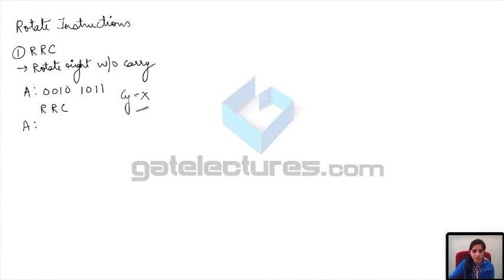The status of the carry flag is don't care for us. When we rotate the contents of the accumulator towards the right, the LSB is going to become the MSB, and every other bit is going to shift right by one place. So what is going to be the new contents of the accumulator? Fine. So this is how RRC is going to work. This is a 1 byte instruction and has only one machine cycle of opcode fetch, consisting of 4 T states.